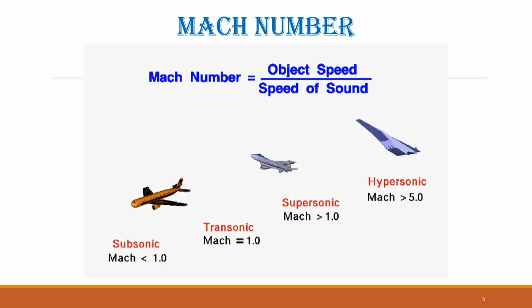Since the Mach number depends on the local speed of sound, and the speed of sound depends on air temperature, which in turn varies with altitude, engineers and scientists use mathematical models of the atmosphere to predict how compressibility effects change at different heights. This allows accurate prediction of forces, lift, drag, and shock wave formation for aircraft traveling at various speeds and altitudes.